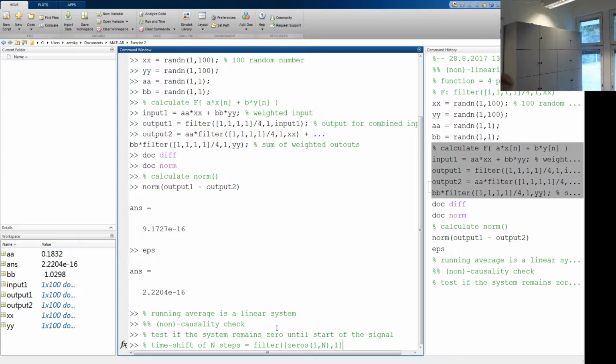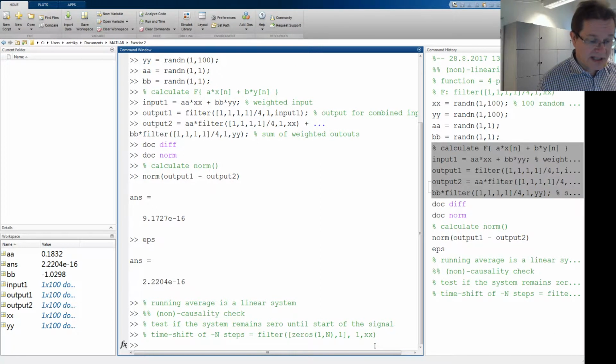Okay, that's time shift, negative time shift. So this is delay. Positive time shift, which means advanced operation, plus n. You need to first reverse order this data, and then actually do time shift and then reverse order it again.